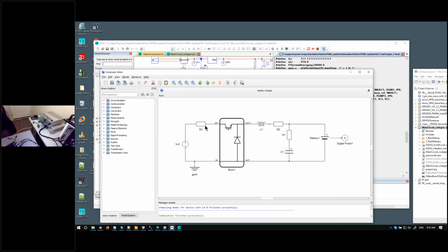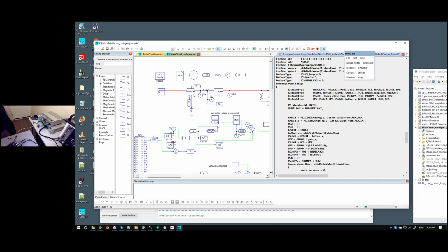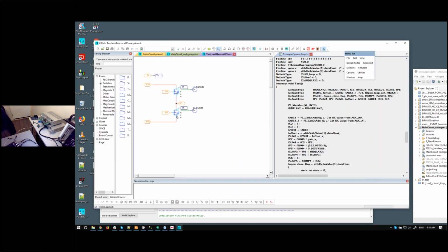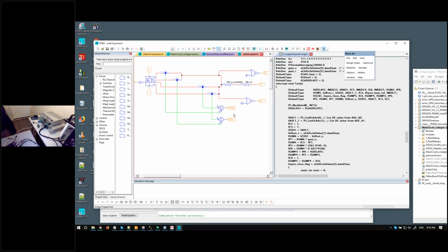So we've basically just a simple buck converter. I don't have a synchronous buck, so I'm not allowed to implement the same switch in the way the HIL system simulates it. So it's just an active switch and a diode, as opposed to if we look back here, it's the two active switches, so the synchronous rectification, again with the thermal devices under the hood.